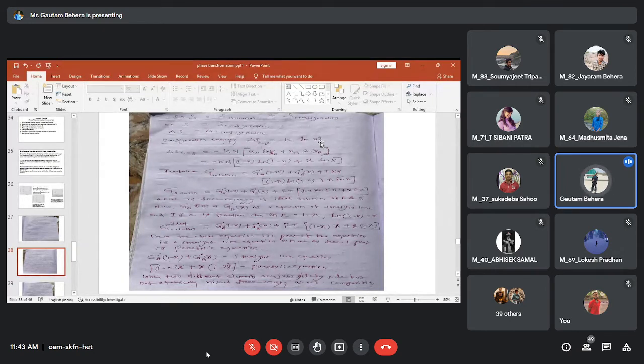Anyways, what I mean to say is, now I want to show you the delta S configurational entropy. Configurational entropy can be written as negative k_B [X_A ln X_A + X_B ln X_B]. Further, you remember what is X_A and what is X_B. X_B is X only, but X_A is 1 minus X, right? We have taken that already. So instead of X_A, you can write 1 minus X. Instead of X_B, you can write X.